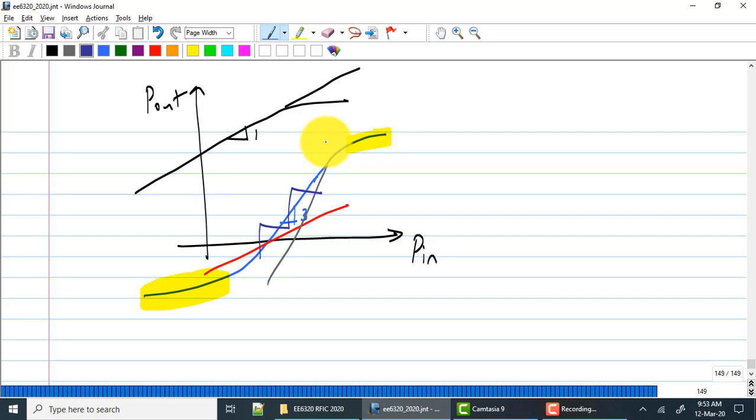At lower VGS minus VT, remember alpha 3 becomes positive, which is when you have gain expansion, right? So if you choose very low VGS minus VT, you might see gain expansion, and that's fine as long as it's not too large. Make sure it is not, a few dB is okay, 2-3 dBs of gain expansion is okay. And obviously there it is not 1 by 1 or 3 by 3. Extrapolate from the region where it is 3 by 3.